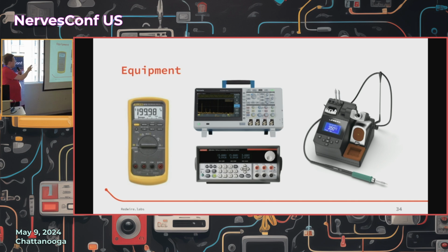So one of those things here, kind of like talking about that data sheet, is some of the things you need to know going into firmware if you're doing that part of the discipline are the tools that come along with that discipline. And so at this point, it's more than just software. There's a good portion of software that you have to work with. But you should also know and be able to work with things, like a multimeter, like an oscilloscope. You should probably have a good power supply, because how many times do power problems cause intermittent issues or flaky issues, or actually the Raspberry Pi power cable is a good example of that. I can't quite remember it yet, but I see head nodding, so you all know what I'm talking about. You get the wrong cable for the Raspberry Pi, basically, and it doesn't power on. And soldering can also be good to know, too, a little bit.